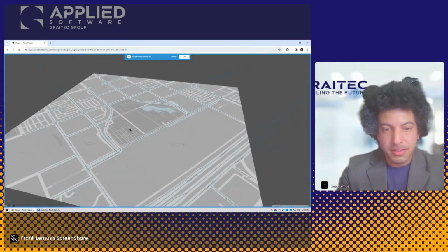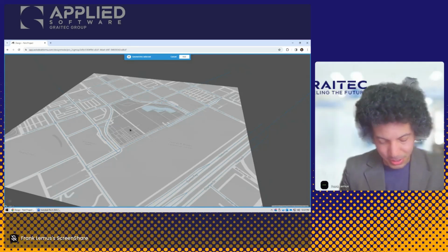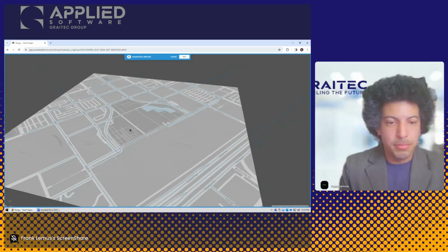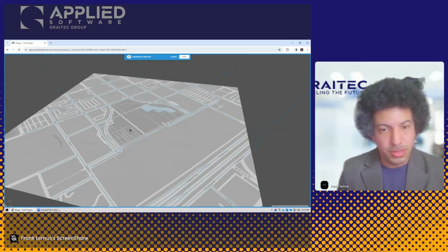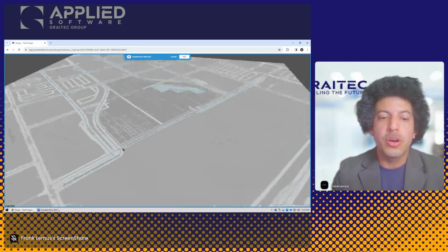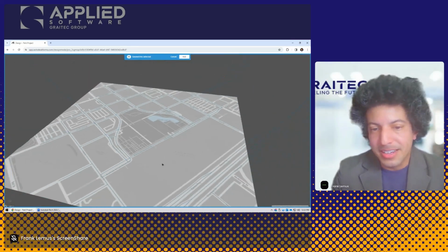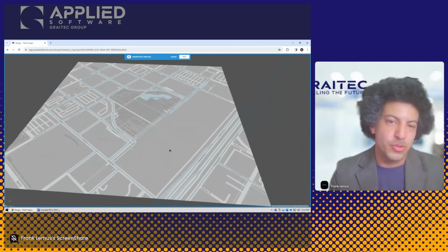If I hold down the Shift key, yes, I know I have a problem with that too because there we go again with Revit. In Revit, Shift means deselect, and Control means to add to your selection. Well, in Forma, you got to get used to the opposite. Actually, there's just one button. It's just Shift. So if you hold the Shift key, then you can add extra things, or if something is already selected, you can click on it to deselect it or click to add it. Okay, so that may be one of the things that they might try to improve on is the user interface.